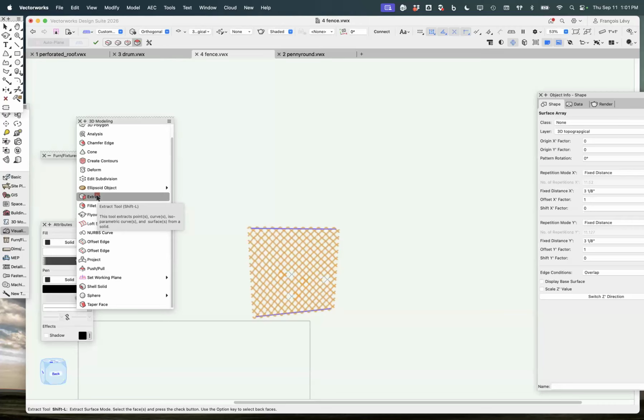I'll play with that. We're seeing you demonstrate it sometimes, but I'll try it on my own too. But Francois, it needs to be a NURBS surface that you're arraying on, correct? It could be a rectangle, it doesn't have to be a NURBS. Okay. Yeah, it can't be a generic solid. It can't be a solid. It needs to be something that has a thickness of 0. Gotcha. Or no thickness is probably a better way of putting it.